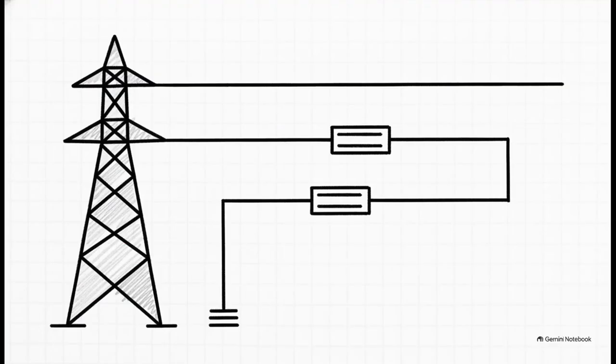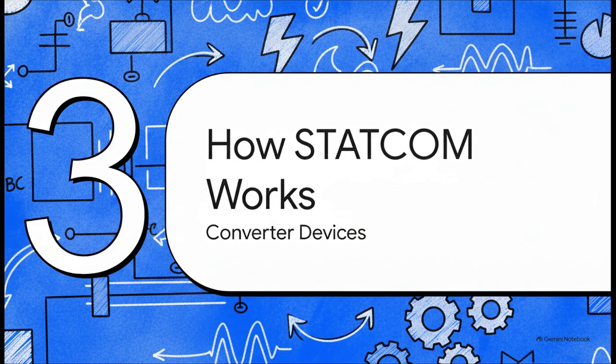So how do we physically balance and support these huge transmission lines? Grounding this whole abstract concept of grid compensation usually boils down to just two things: adding capacitors in series or adding them in shunt, which is really just a fancy way of saying in parallel. Sure, reactors get used sometimes, but it's mostly capacitors doing the heavy lifting here. When we talk about flexible transmission, we are fundamentally talking about exactly how we manage these series and parallel additions to keep the whole system perfectly stable. Now, what's really interesting about this next technological marvel is the shift in approach. Let's look at Section 3, how STATCOM works.